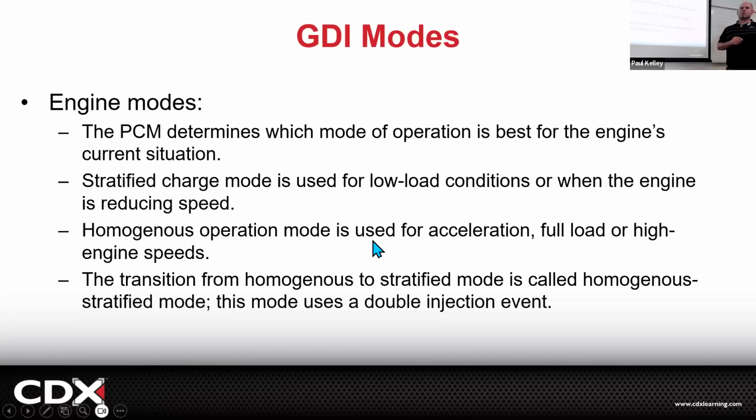So this is so nice for power. The direct fuel injection has more power. There's no argument. It's not even close. We can fine tune that exact air-fuel ratio so that we can get the most advanced timing and not have the pre-ignition and get the most power. These cars run really good, assuming everything's in good condition though. So that's a positive of it.